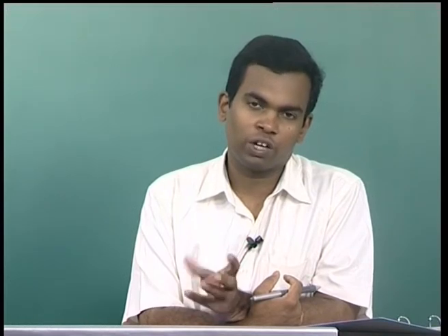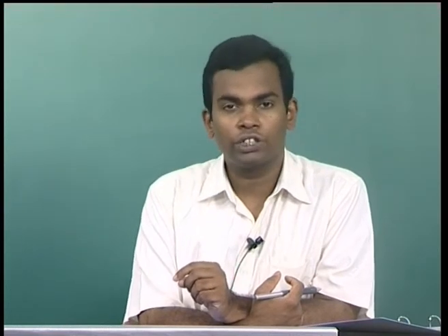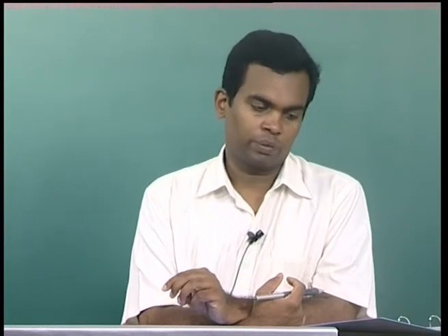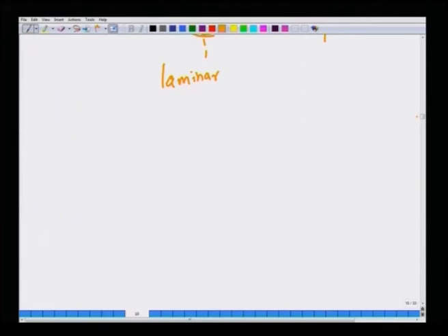In fact, it runs counter to our normal intuition that turbulent flow should have more drag, but here the reason why the drag is reduced is not because of reduction in skin friction, but it is in fact due to the reduction in the form drag because of the fact that the separation is delayed on a turbulent flow past a sphere. So that is the reason why we have lower drag in a turbulent flow compared to laminar flow.